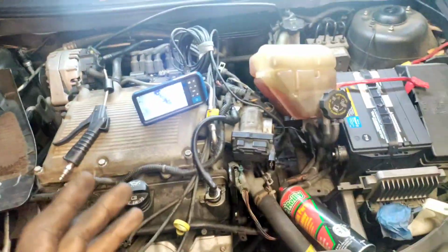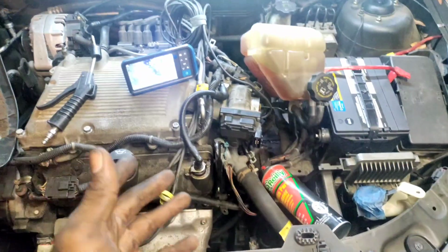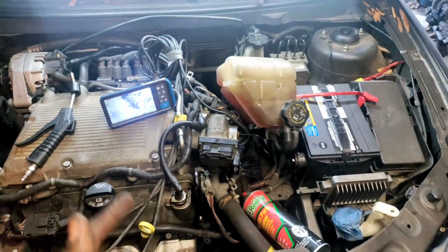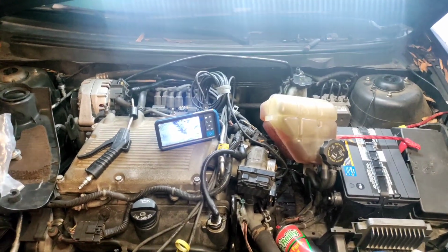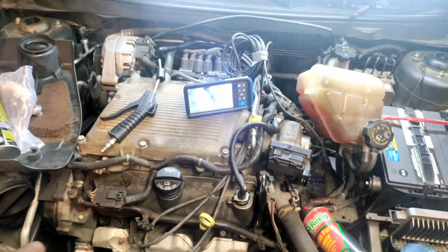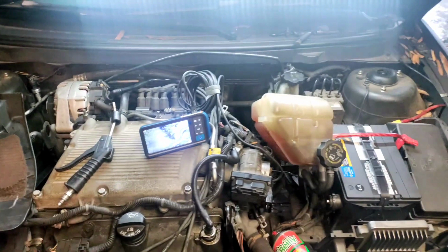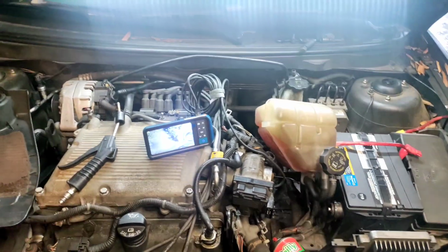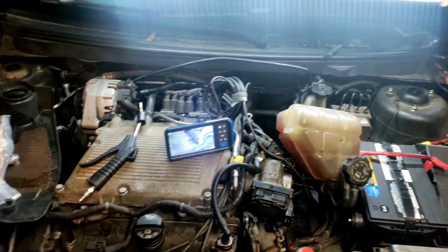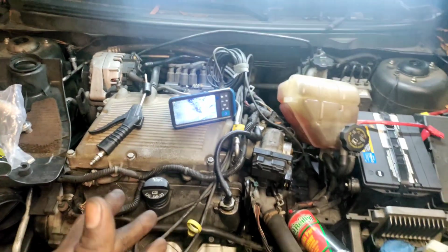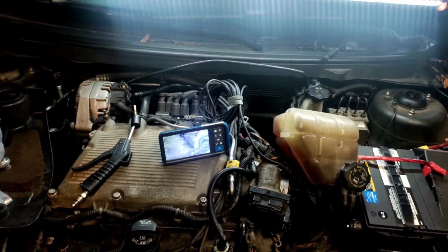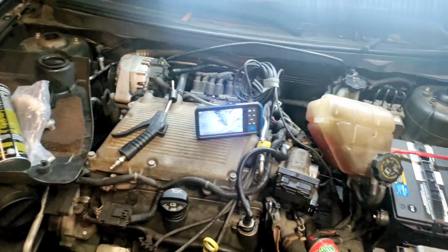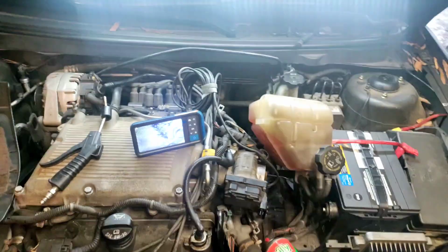Now I probably could just leave brake fluid in there overnight, and I do have something else I gotta work on, so I probably could just let it soak. I know I said earlier brake cleaner probably ain't gonna do nothing, but brake cleaner will break down sludge buildup, and I've tested that before personally. But it will just have to sit for a while, and you will have to agitate it in some way. So after a while it will loosen it up. But as far as clearing an obstruction, you need to be able to get to it and disturb it or agitate it for it to be effective.